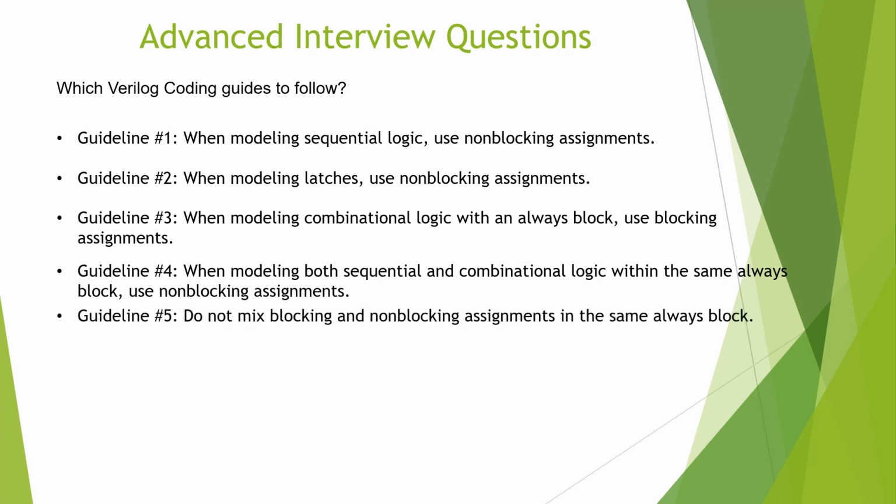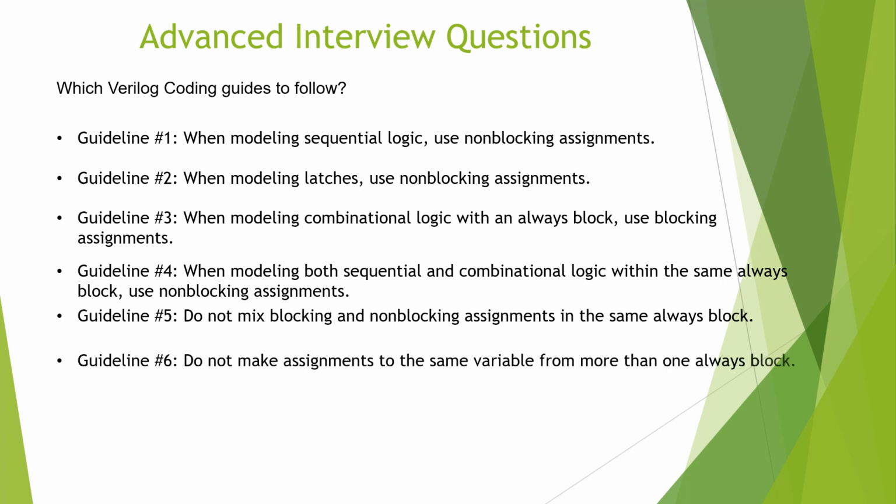Guideline number five, do not mix blocking and non-blocking assignments in the same always block. It is self-explanatory that you do not mix blocking and non-blocking assignments in the same always block because it is tough to read and also prone to bugs. Guideline number six is do not make assignments to the same variable from more than one always block. When multiple drivers to the same net exist, then the synthesis also gives you a warning.